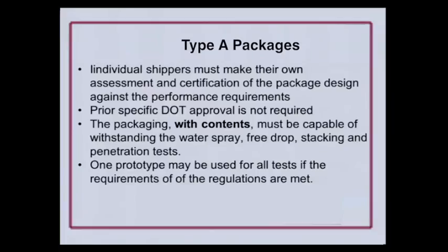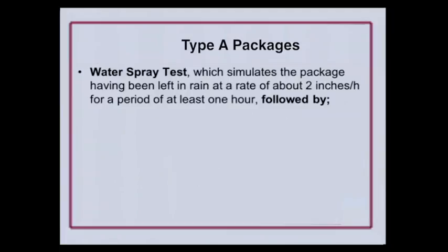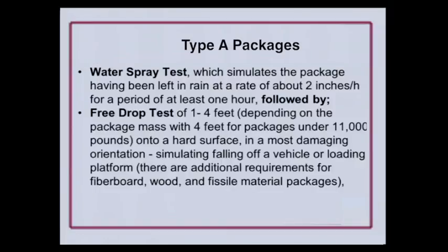You don't have to do each shipment. Now, if he were to change and use a different manufacturer box or something like that, you have to repeat the testing. And as I already said, the water spray test must precede each test. Just as a reminder, the water spray, left in rain, about 2 inches an hour for a period of at least 1 hour, followed by a free drop test, which I don't think we showed, 1 to 4 feet, depending on the mass, onto a hard surface in the most damaging orientation.